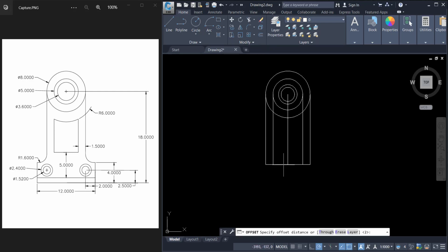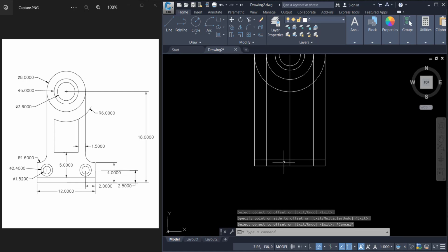I'll click on the offset tool. What I want to offset this line for is to make this one. You can see that this one here is about 1 meter. So I'll offset this particular line by 1 meter. Click enter. Offset this one. Escape. Okay, so we've just accomplished this.